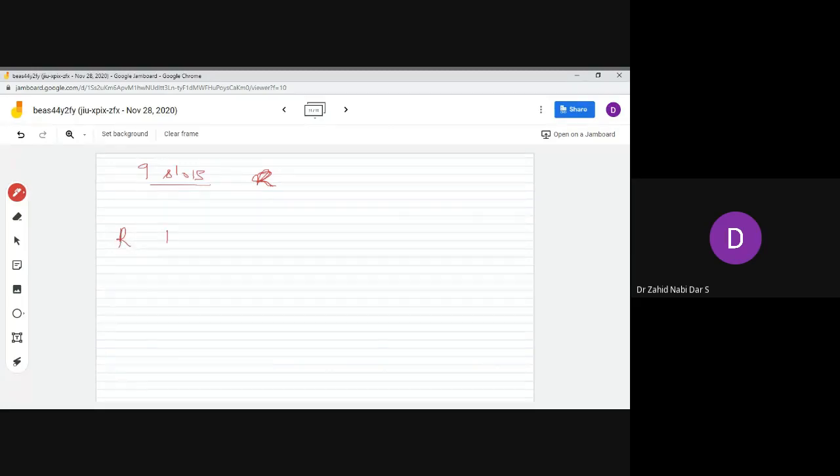And the coil span, like coil per phase, so every winding would have essentially 3 slots. So first red I will give 1, 2 and 3, okay. Then I'll write my blue, I'll give 4, 5 and 6, and then let's take green, okay. Red, blue and yellow only, yellow I'll give 7, 8 and 9.